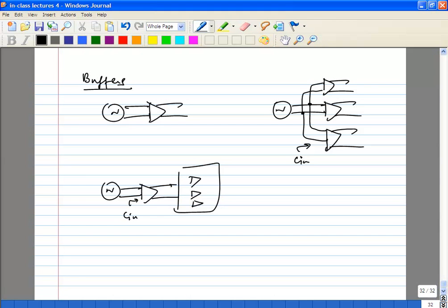The other thing this 2-stage buffer helps you with is kickback noise. The circuit which this is driving will typically be a divider, or it could be a mixer. Definitely the divider is going to be switching; it's a switching digital circuit in most cases. So now you have to worry about kickback affecting your VCO. So obviously if you have a 2-stage buffer, it helps more, your reverse isolation is better.